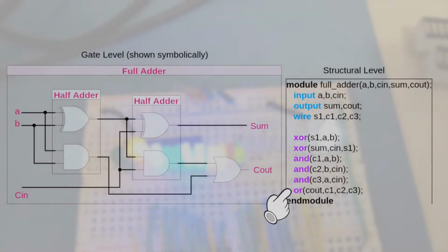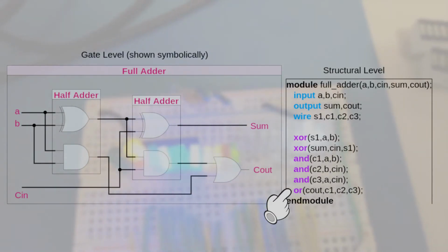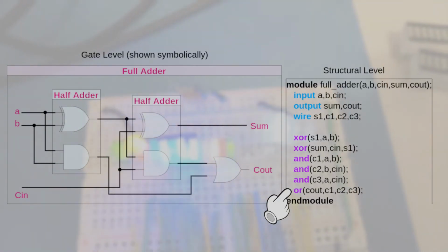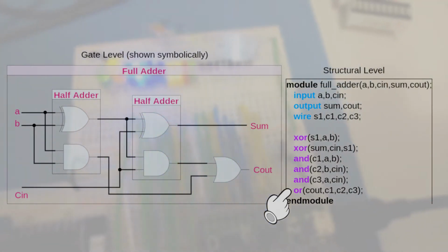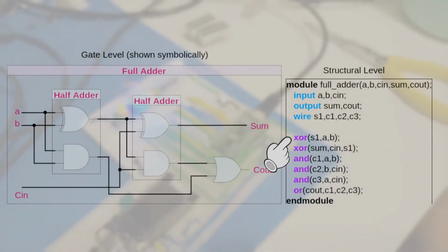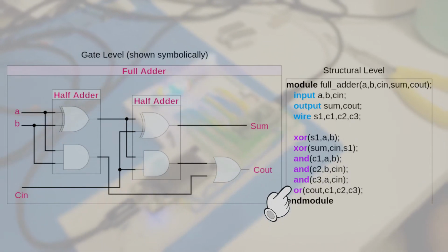Now before we start building our module, let's take a look at a couple of different approaches to modeling within Verilog. We could build our ALU using gate level modeling. On the left we have a very simple adder to stand in for the ALU. On the right is what the Verilog would look like. Notice the explicit use of gate level constructs such as AND, OR, exclusive OR.